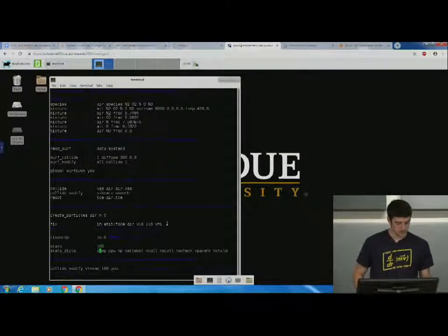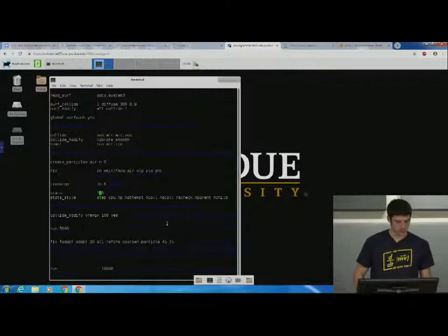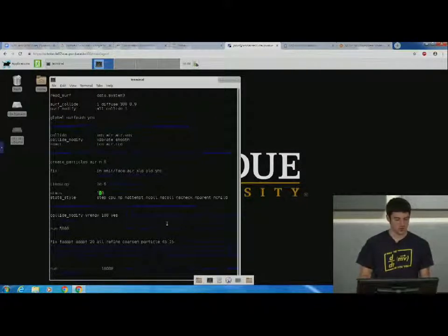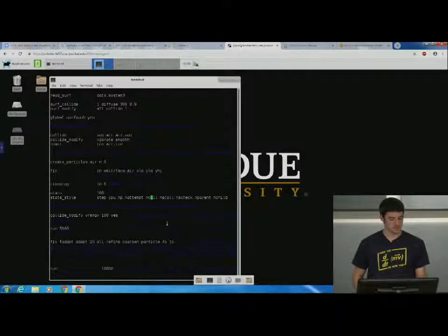And then here is the thing. We're done specifying the problem. Now we're trying to get some diagnostics. When SPARTA runs, in this case we're saying stats to output, tell us what's going on every 100 steps. Just a generic idea of how everything is running. So every 100 steps, it's going to tell us the step number, the CPU time, number of particles in the domain, number of attempted collisions, number of collisions, and so on and on.